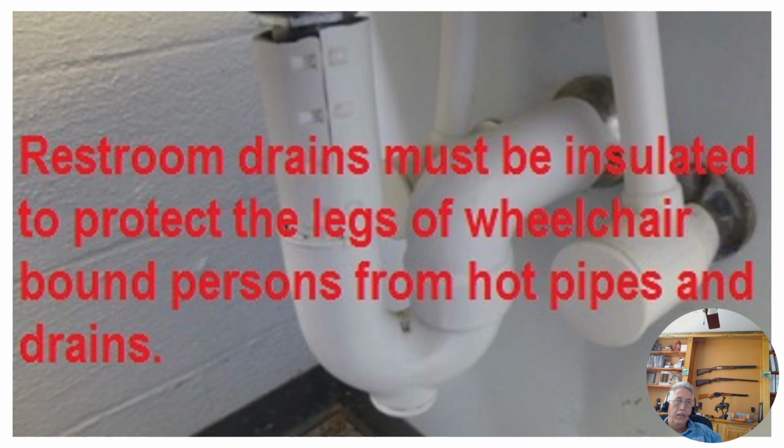Electric's good. So here's the difference. You have to have your plumbing underneath insulated with these. They're kind of a bumper pad and insulation. Someone in a wheelchair might be paralyzed, right? And if they roll up to wash their hands, this P-trap does get pretty hot when you run just hot water, and the hot side valve will get very hot.